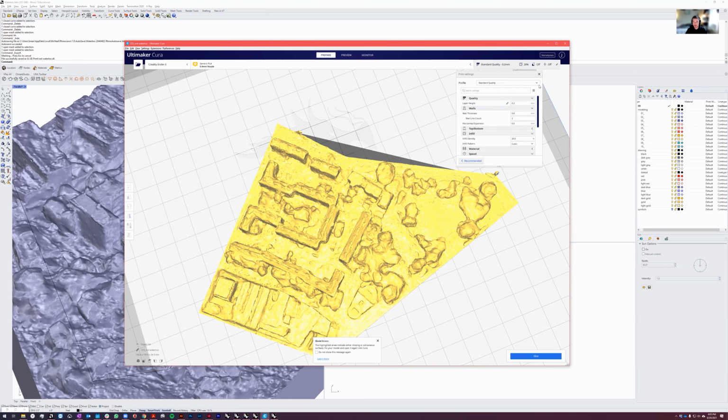I probably don't need to show you print settings. I'm just going to do standard quality. I'm going to turn the print speed up to 60. And I don't think we need, yeah, just do a skirt. And I'll do a grid. Doesn't need to be very, very interesting. Supports, no support. Yeah, I'm gonna leave supports off in this. Okay, I think that's good. So let's slice it.